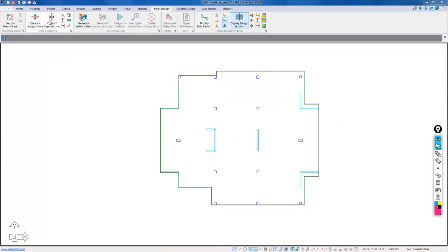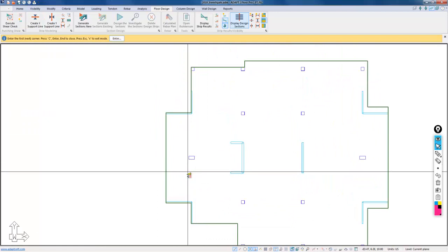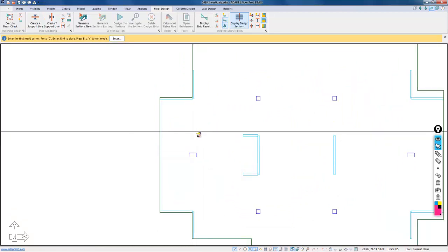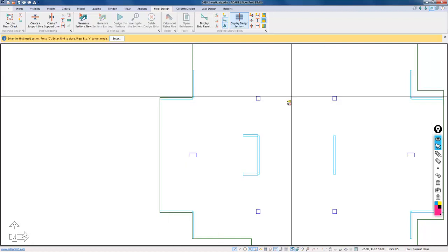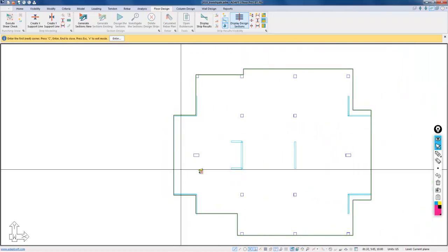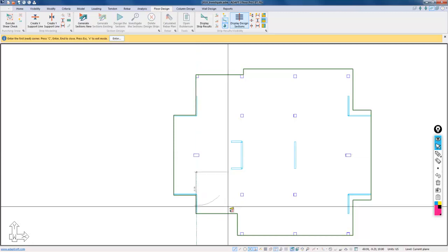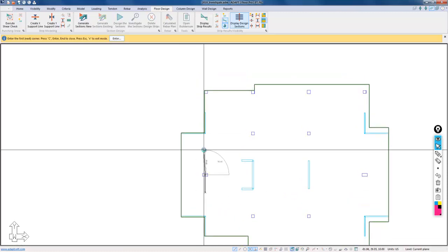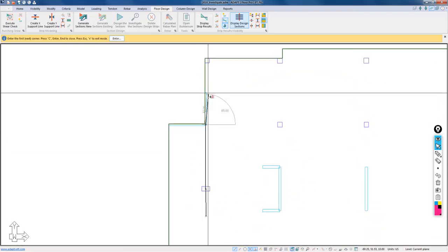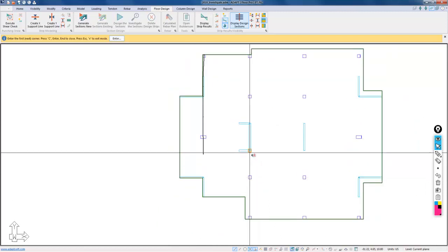I'll go over here now to Y direction, and I'll say, okay, create the Y direction strips. And for this direction, I'm just going to start again somewhere below this frame line. All I'm worrying about really is this area here. So I'll actually start back here, and I'll click a point as my start point. I'll turn off snap orthogonal because that becomes cumbersome in this case. I'll snap to the endpoints of walls to the column, and then I'll stop this at the slab edge, press enter, and begin drawing my next one.